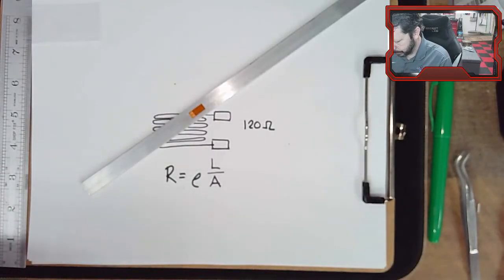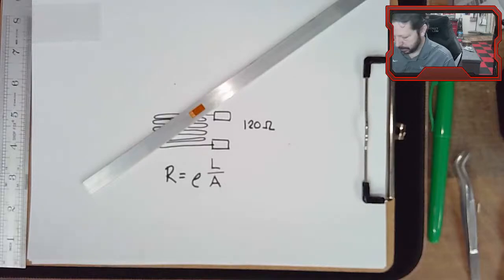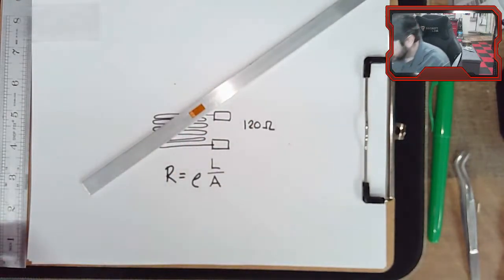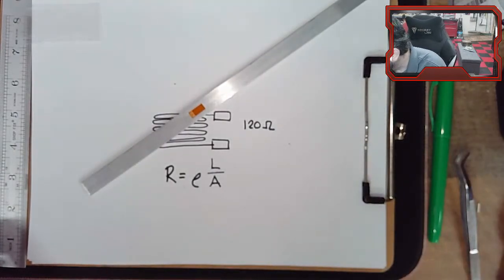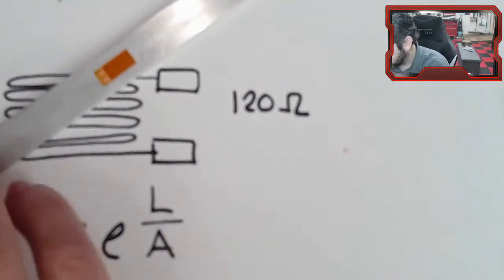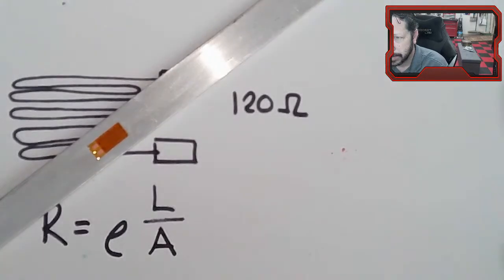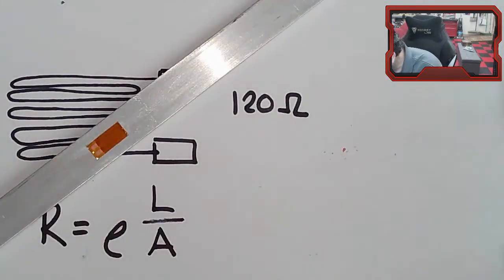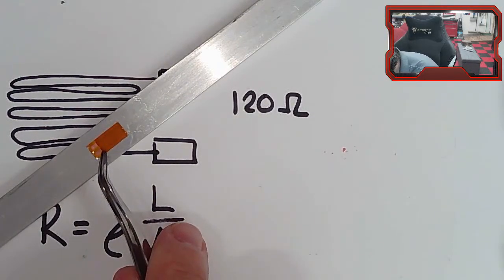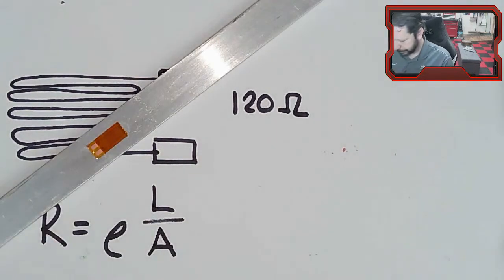The next thing you could do, assuming you glued it in the right way, is that when we go to solder on here, we can burn the pads off. So let me show you. Zoom in closer to this guy. If you burn off a pad, there is a little bit of a pad underneath this film right here that would still be left, and you can scrape the film away and solder to that if that ever does happen. Hopefully none of that happens though.